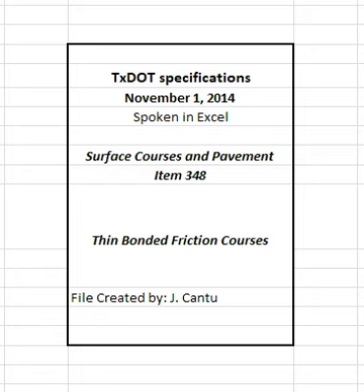2.6.1 Fibers. Provide cellulose or mineral fibers when PG binder is specified. Do not use fibers when AR binder is specified. Submit written certification to the engineer that the fibers proposed for use meet the requirements of DMS 9204, fiber additives